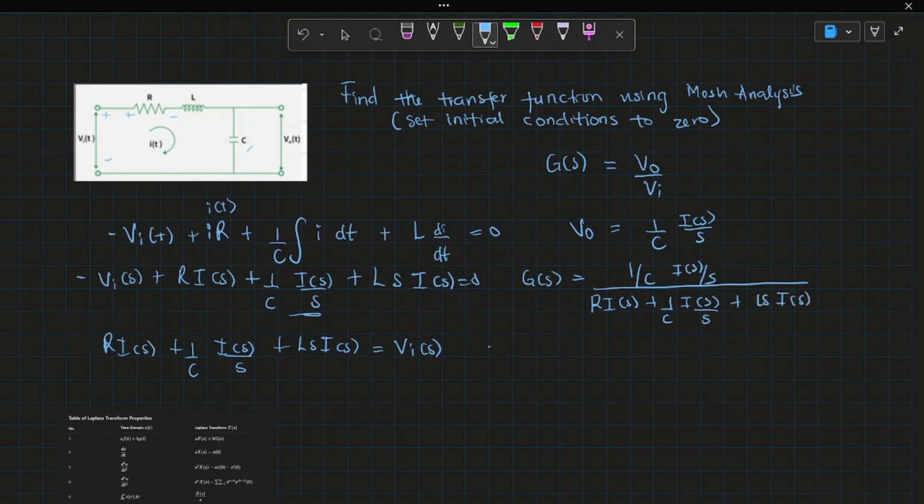So just like this. Now, the truth is, when we're writing transfer functions, you don't really want to be seeing negative powers of s. So you don't want this. So we have to try and simplify this in a way that we won't be getting that. So we can multiply through with C s over I(s).